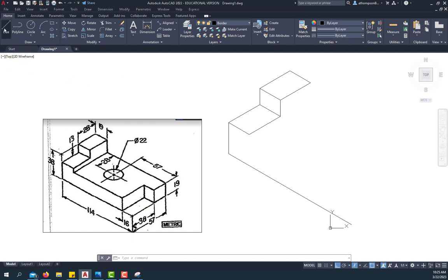So again, we'll go to the line command. We're going to make a line over top of a line, but not to worry, we can delete it out. I'm going to have to hit F5 to get it to go in the direction that I want. So I'm coming back here in this width and I'm typing in 16. Enter. Even though my mouse was way back, it only went 16. So it doesn't really matter where your mouse is as long as you're typing in distances. And then I'm going to put my mouse straight up, type in 19. Enter.